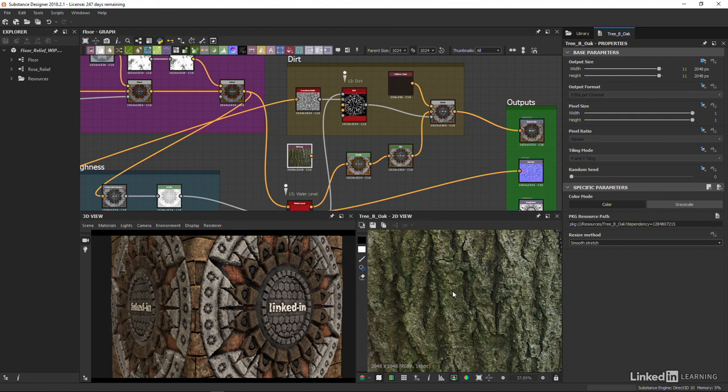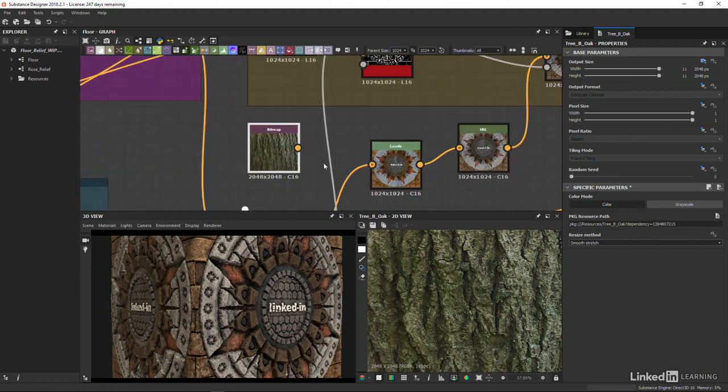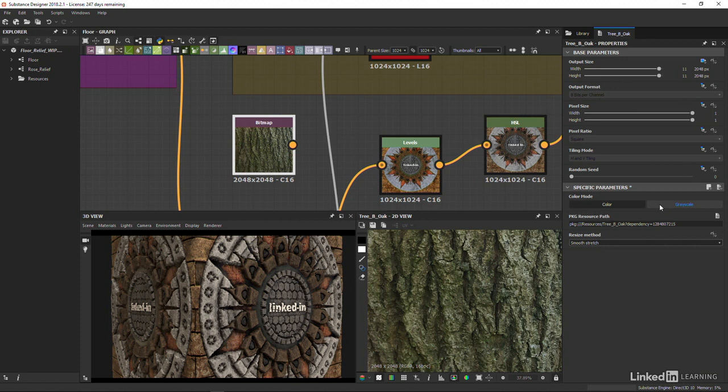As you can see in the parameters section now, we can choose between using RGB or grayscale outputs from our map, which is because some nodes in Substance Designer work in grayscale, using the luminance data in a map to affect changes, whereas others use color information to do the same thing. Having this switching option available then gives us greater flexibility without us constantly having to add a grayscale conversion node to a color bitmap. Indeed, we can see the output circle on the node change from yellow, denoting a color output, to grey as we use the switch, which as you would expect now denotes that the node is using a grayscale output.